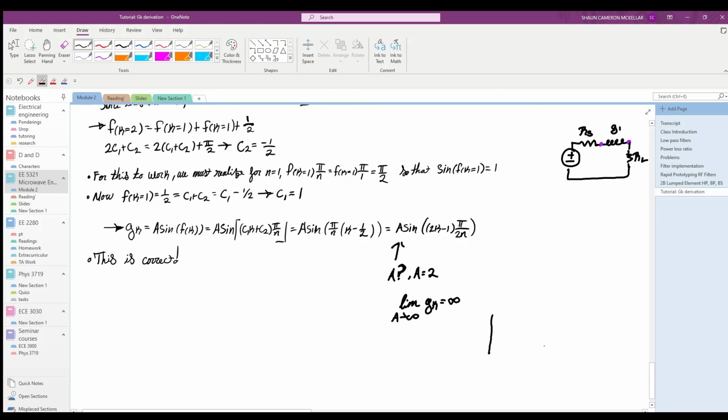And it's going to give us this effect where if we go and graph the frequency response of our filter in dB, at the low frequencies, normally it's going to pass almost all of it and then attenuate heavily at higher frequencies.